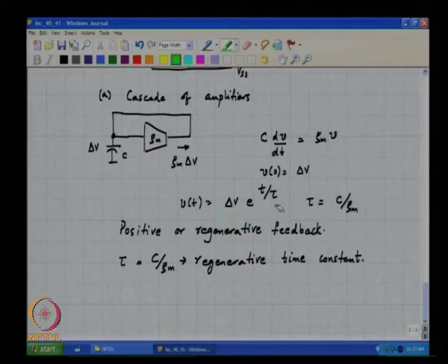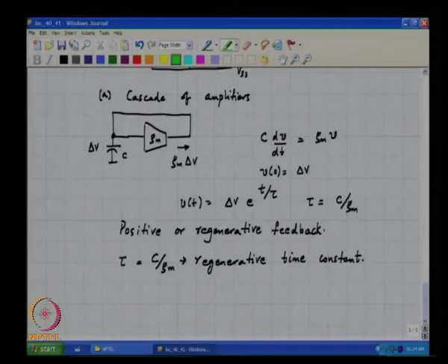So, from a hardware complexity point of view, this is a very simple structure where we use positive feedback to obtain gain, whereas the cascade of amplifiers would have required a whole bunch of amplifiers to do this. You understand? And linearity etc. are not really important. All that we need to do is figure out if the input is less than 0 or greater than 0. So, this is an ideal candidate for doing this.